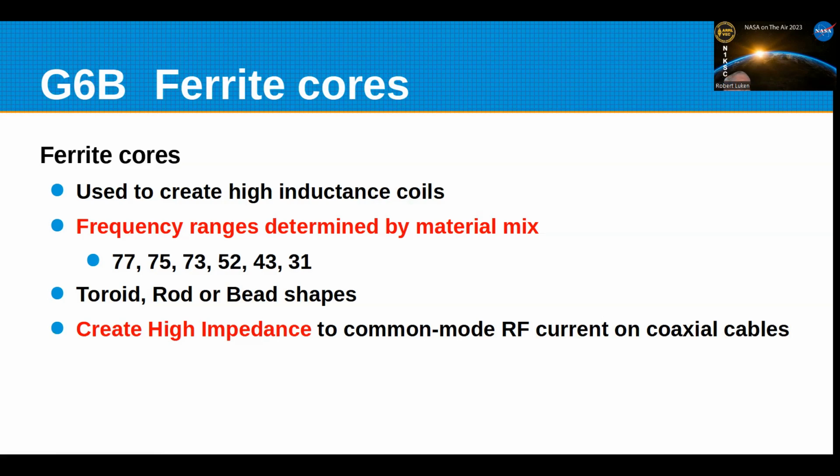And then there's rods, which you used to see in the little transistor AM radios, ferrite rod with wire right as the antenna and input transformer. If you use particularly beads or toroids, you can make a high impedance common mode choke for your coax transmission line, either by slipping beads over it or winding coax around the toroid.